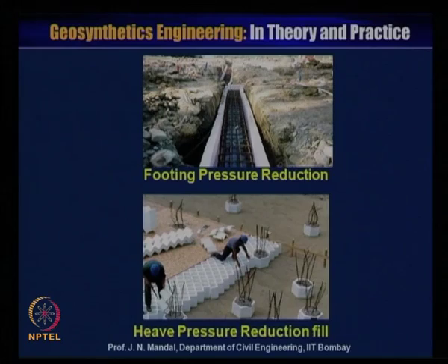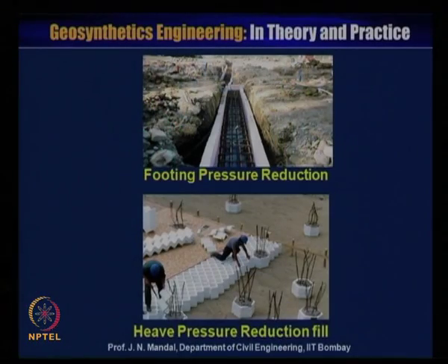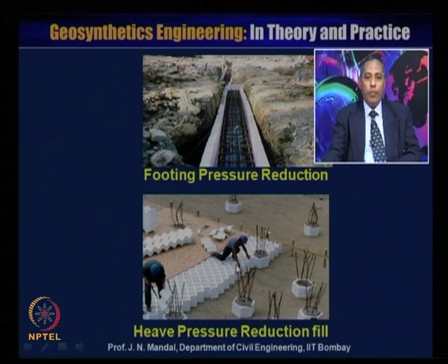So you know how you can use the geofoam below the building or the foundation, and here you can see some of the applications, that is the swelling pressure, how it is reducing. Here the geofoam has been introduced, and here you can see how the heave pressure is also reduced in the field, how the geofoam has been used.